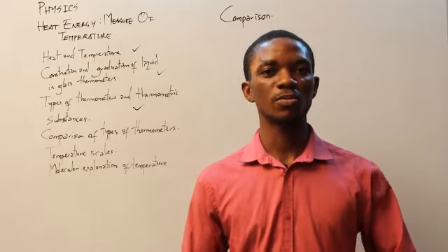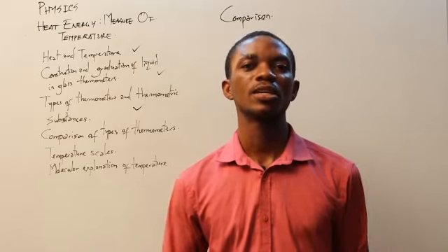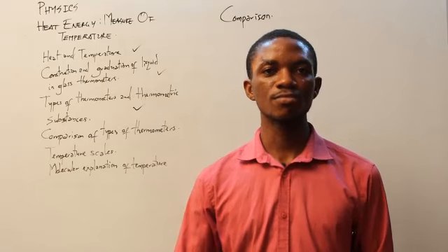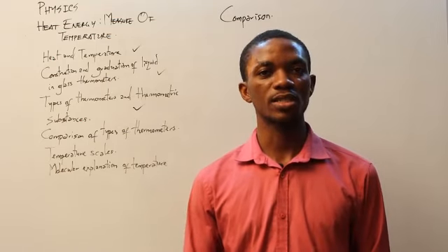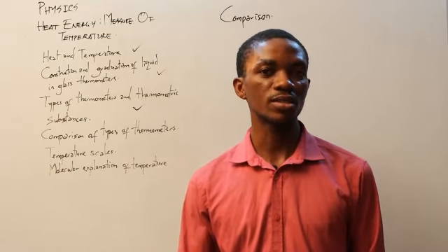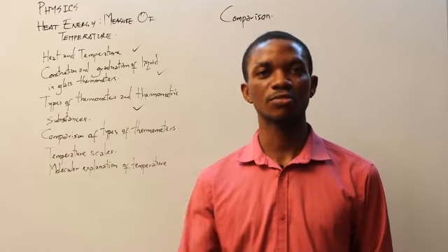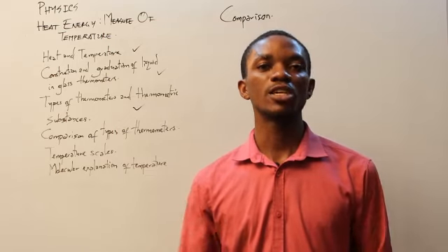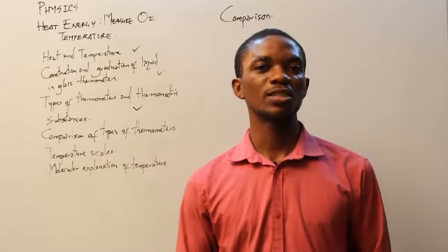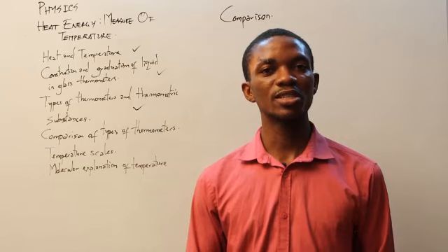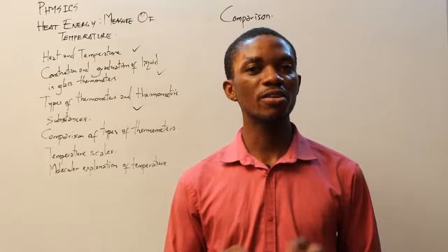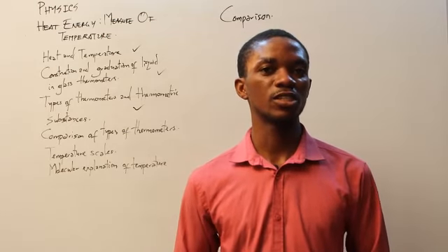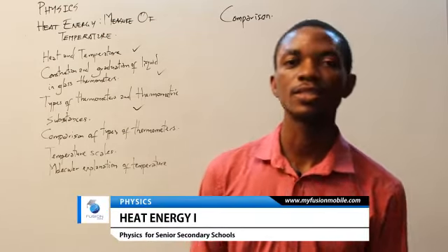The temperature of a particular place can be about 35 degrees Celsius right now, and in the next 15 minutes, it can be as low as 29 degrees Celsius or even 25 degrees Celsius from 35, maybe due to cloud cover or emergence of rain. So the platinum resistance thermometer may not be very good for measuring temperatures that change very abruptly like that.